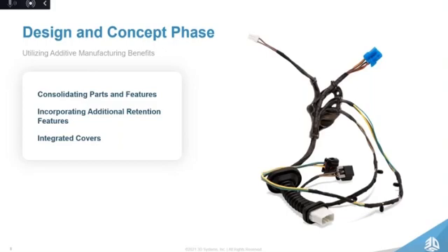The solution choice is often dictated by material properties, and in this case, the choice of material, Figure 4 Rigid 140C Black, is the ideal solution. Rigid 140C Black is a new high temperature material, as the name suggests. It's a rigid, heat-resistant material combining high strength and high elongation for toolless direct plastics production. Next slide, please.